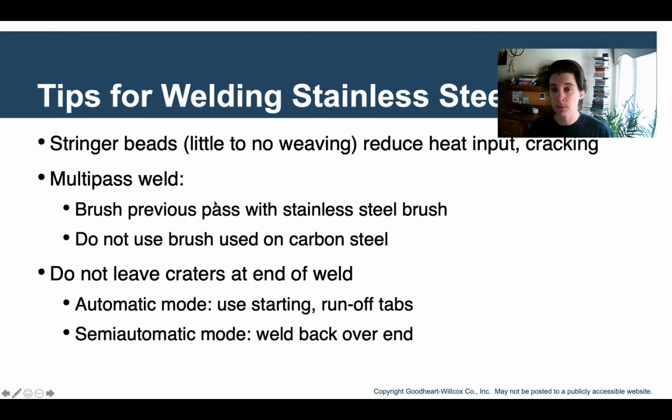For a multi-pass weld, make sure you brush it, clean it with that stainless steel brush that hasn't been used on any carbon steel. And don't leave craters at the end of the weld. That's where you stop at the end of the weld quickly, and there's a little bit of concavity in there. Make sure that you fill that back in, because that can create a weak point where stainless steel can be more prone to cracking than it would be with carbon steel. You can use a runoff tab, so you weld past the main weld that you are working with, so you don't have any problems with the start and the stop.